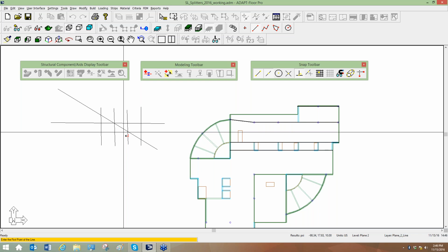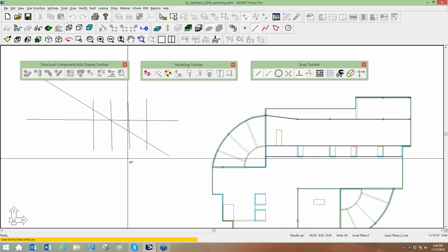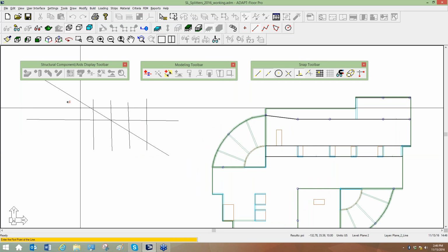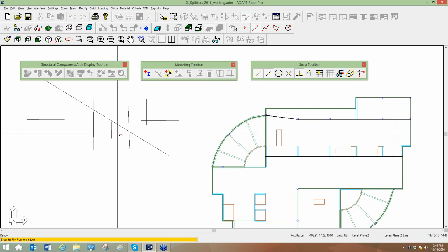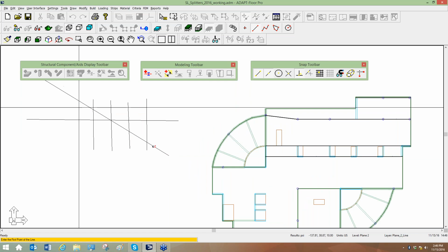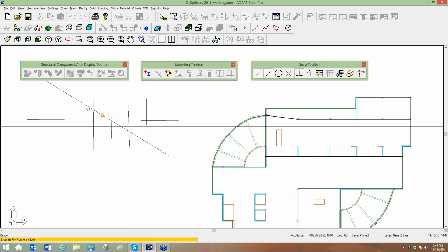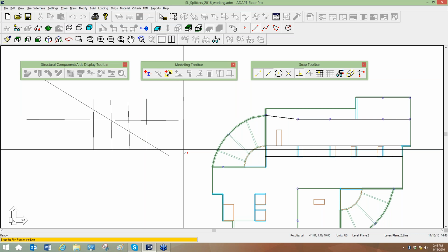That not only affects the stresses, let's say, but it also will affect the rebar. How much rebar this section has in terms of capacity generated from the PT. It doesn't have full capacity. It only has a percentage of the capacity of PT because of how it's aligned with the banded tendon.